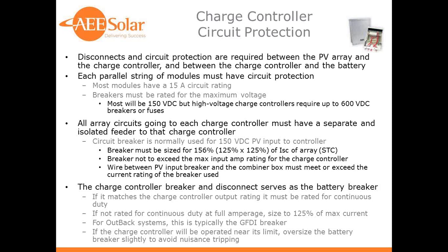All array circuits going to each charge controller must have a separate and isolated feeder to the charge controller. Each controller has its own PV array. It's isolated from other controllers and other PV arrays.